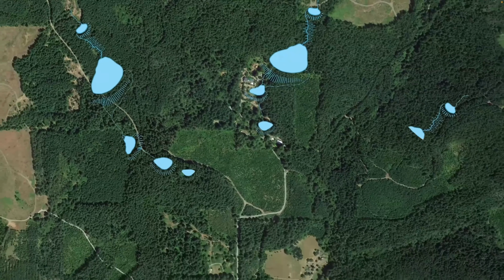And you may even see, after you've dug your test slice, that water is cascading down the side of that lower soil horizon. That would be a soil with higher clay content generally. And if you get into the subsoil and find that you have deeper layers of heavy clay, this is the material that you're going to be using to build the core elements of your pond and using to seal the pond. You want to dig a bit deeper than the planned pond depth in order to see what the entire layer of soil looks like below the pond.